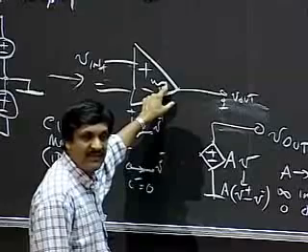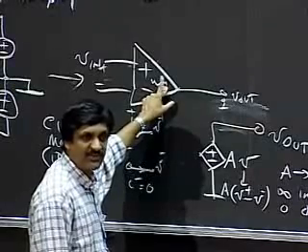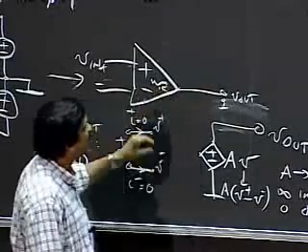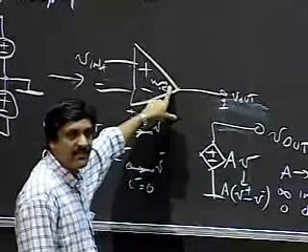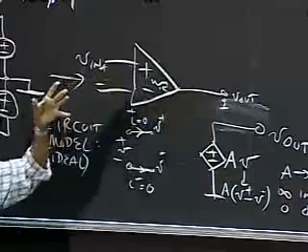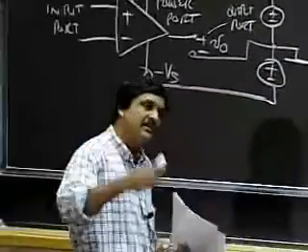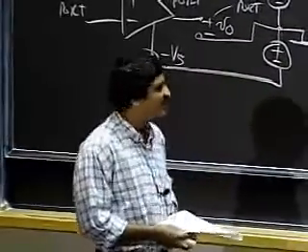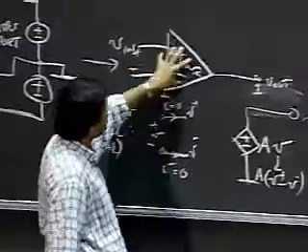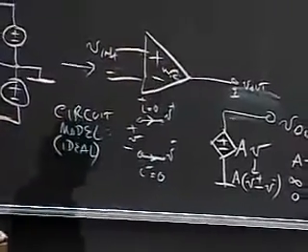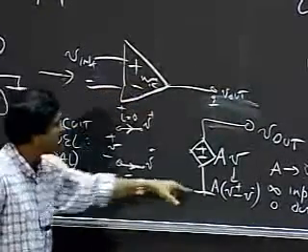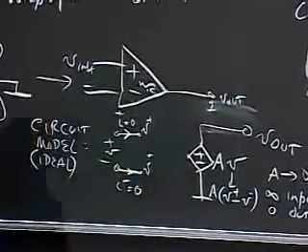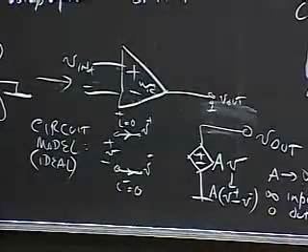You saw a variant of the source follower on your quiz as well, in problem 2. So a circuit that looks like that appears at the output. Remember, for the source follower, the resistance looking in from the output was very, very small. So you have seen some of the pieces that go inside the amplifier, but we will deal with this as a building block and simply represent it using this little abstract circuit.